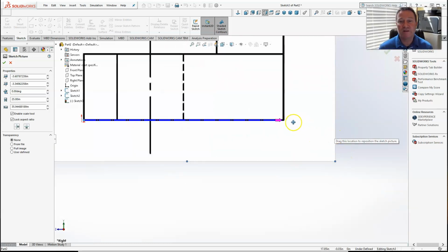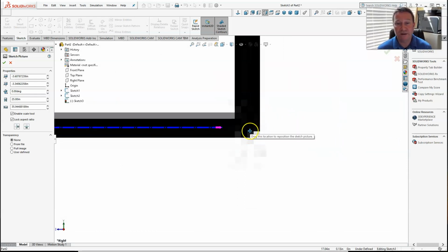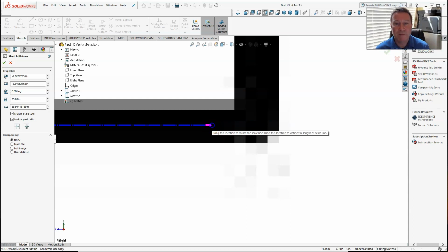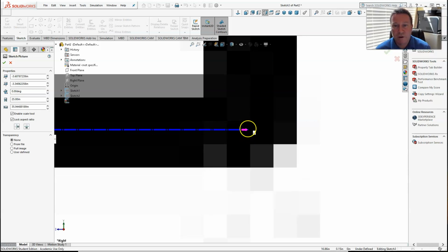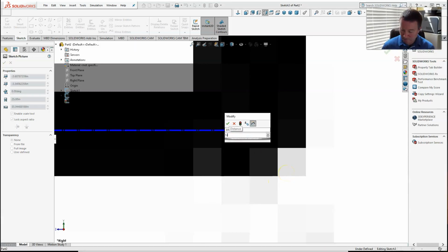Take your time. Try to get as close as you can to the center of the horizontal and the vertical lines, because the closer you are on all 3 of your image files that you import into the sketch plane, the more it'll help with your part creation when you scale. It doesn't matter which plane you use, front, top, or right side. If you scale on any of them, it should come out really close to what the actual values are supposed to be. There, 1.5 inches.